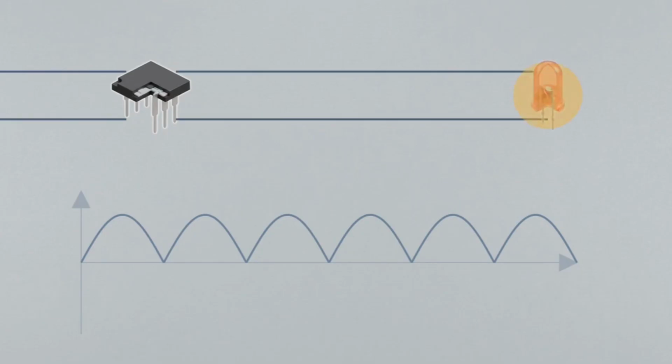To bridge these gaps, engineers insert a capacitor into a parallel circuit line immediately after the rectifier. As the main waveform hits its peak, the capacitor charges. The moment the supply voltage begins to drop into the zero voltage gap, it automatically discharges its stored energy. This precisely timed release of electrostatic energy fills the troughs, flattening out the erratic electrical peaks into a continuous output.